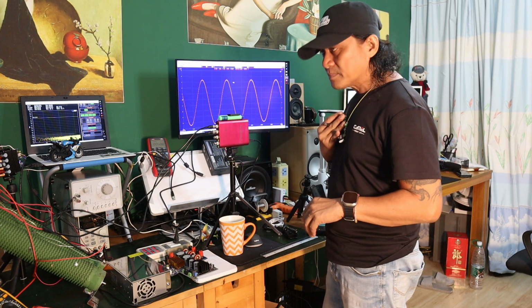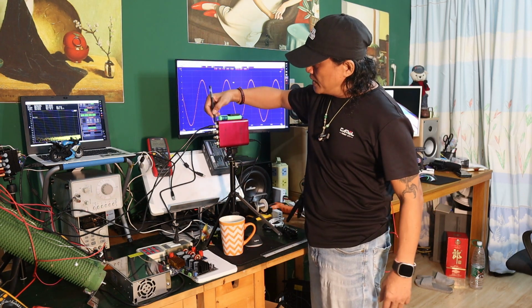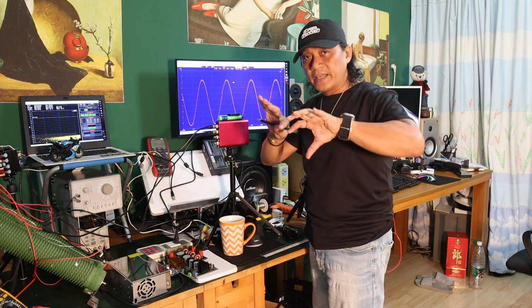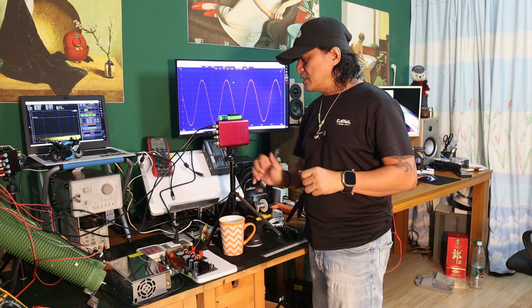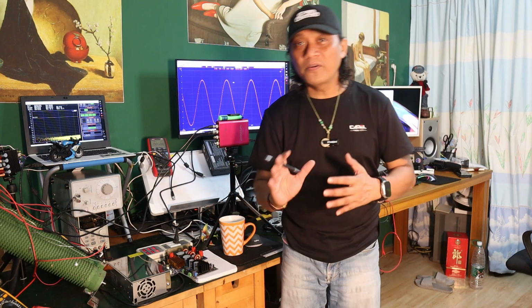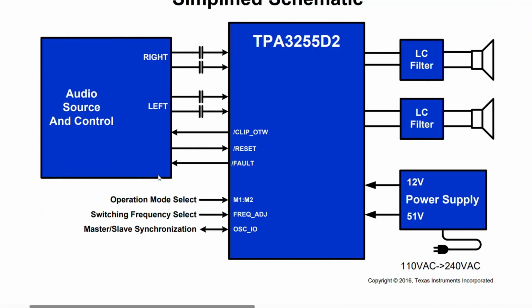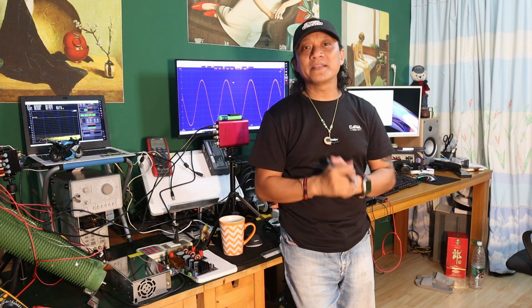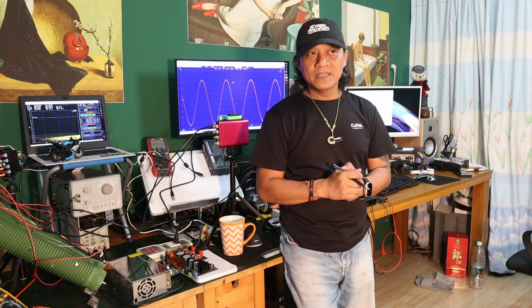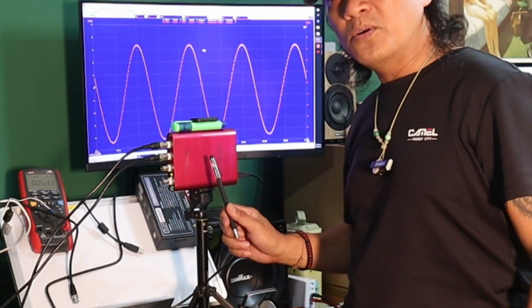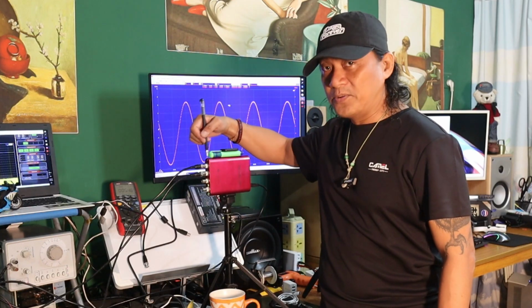My belief right now is that the BNC GND is connected to each other, and it's not separated or floating, and that is the reason why I got the trouble. But I didn't know that before, because all I knew was I'm looking at the Class D power amplifier, that Module B, that BTL is basically no polarity, and that's the culprit. My mind is focused on that. I'm not focusing on how this DSO 2A20E is connected.